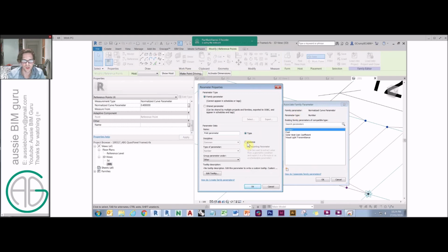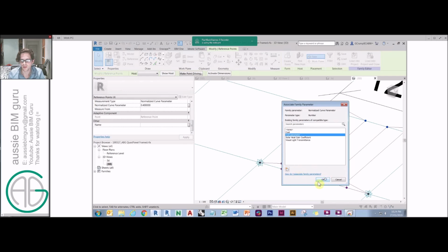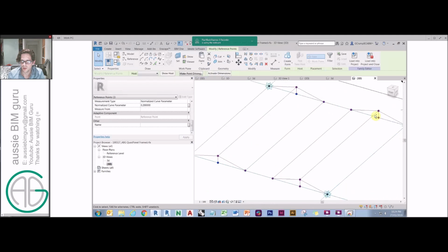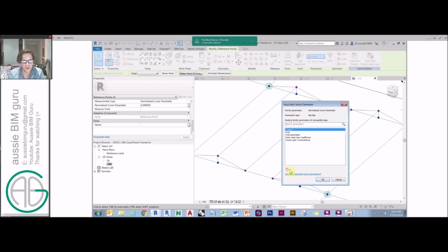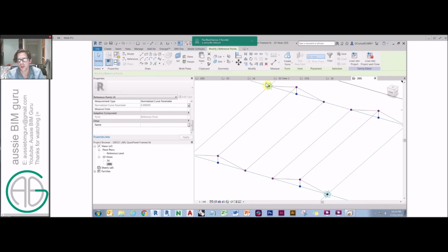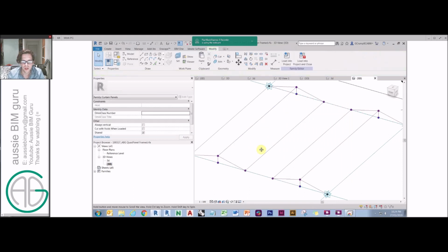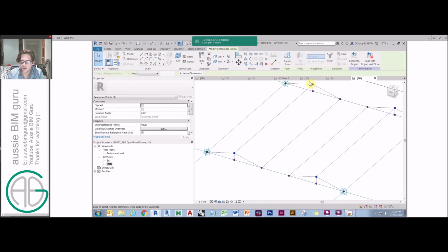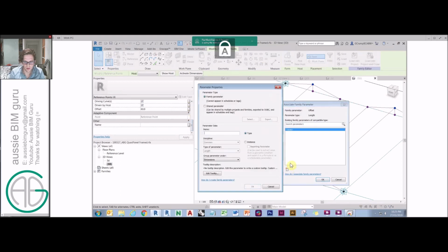We will jump ahead to another version again, which will probably have different names for these parameters, so don't get too used to the names of these ones. Likewise, we'll do the same for the mid parameter. And we'll take that one, and we will call that half fold. And we're making these instance based because we want every panel to be individually adjustable. And then beyond that, we'll take all these points and give their offset a parameter. Under here, fold offset.